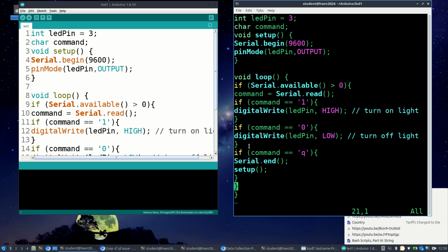Now, that resistor, you're going to want to connect to the LED. So the long leg of the LED needs to go into the same node as the resistor, okay? I'll make it bent. And then the short leg needs to go into some other row, some other node.